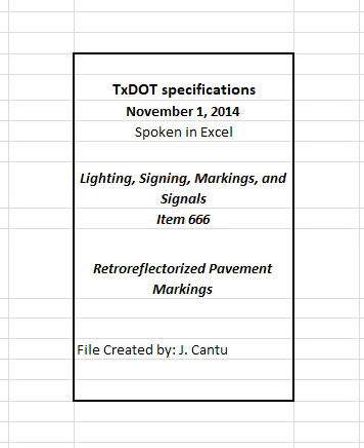4.1 General. Obtain approval for the sequence of work and estimated daily production. Minimize interference to roadway operations when placing markings on roadways open to traffic. Use traffic control as shown on the plans or as approved. Protect all markings placed under open traffic conditions from traffic damage and disfigurement. Establish guides to mark the lateral location of pavement markings as shown on the plans or as directed, and have guide locations verified.